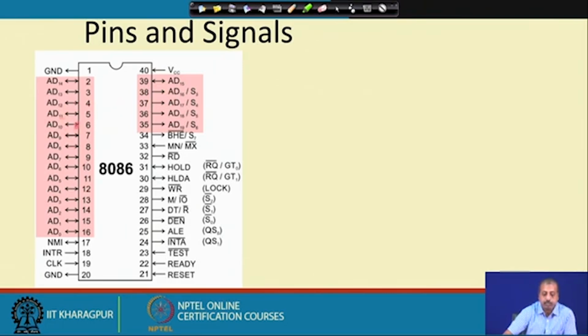Okay. So we have a 16-bit data bus, AD0 through AD15, the D0 to D15, but we also have some more lines. Though the names are given as AD16, AD17 and so on, they are only address bus pins, and they are multiplexed with some more status pins S3, S4, S5, S6. So these 4 status lines are multiplexed with this address bus. That is why none of the address bits are free. They come as a 20-bit address and a 16-bit data bus.